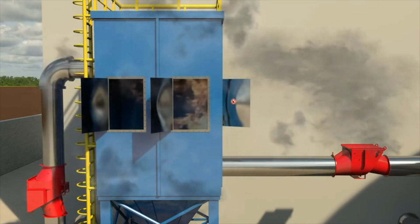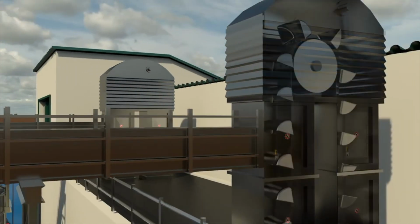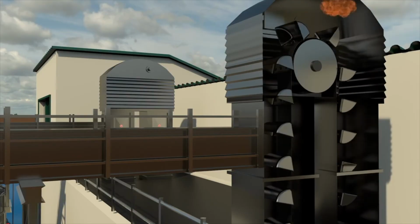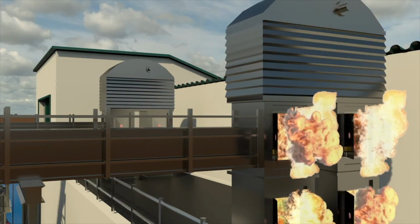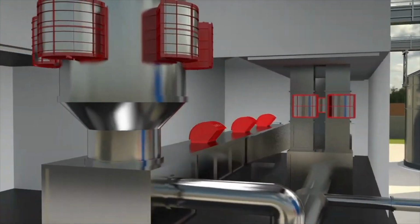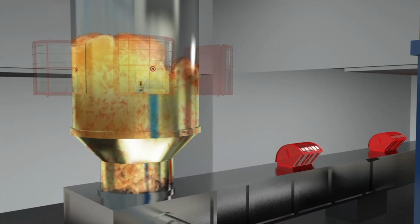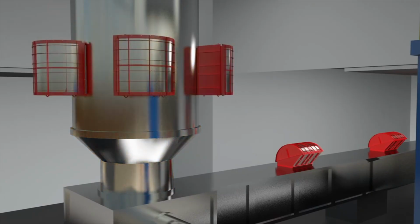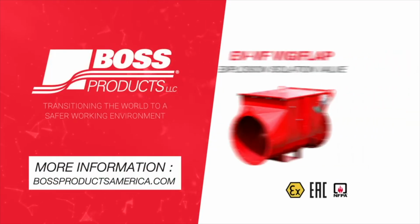There's the venting. Those are some flat panels on an elevator. And then some flameless vents. The panel bursts, and then the fireball, like I mentioned before, gets quenched by the layers of stainless steel mesh, and all you get is smoke.